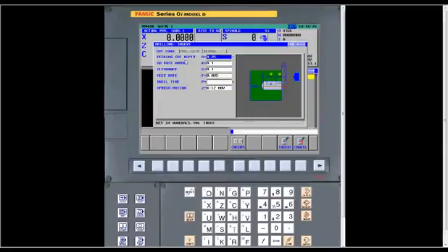What it's asking for is pecking cut depth, and you can see it has Q highlighted. That's like if you're doing a G83 drill cycle where you want the drill to fully retract; that's the amount of each peck. Then the go past amount, that's just to allow for the angle on the drill. The clearance is like an R plane at the start of a drill cycle. Your feed rate, and dwell time, which again has an asterisk. You do not have to answer that information, but that's like dwell time at the bottom of the hole. If you wanted it to dwell for a part of a second, you could put that in.